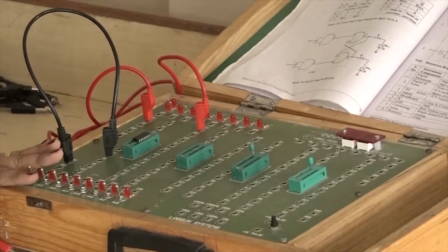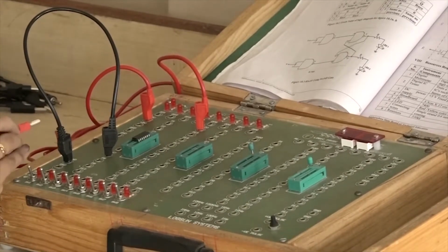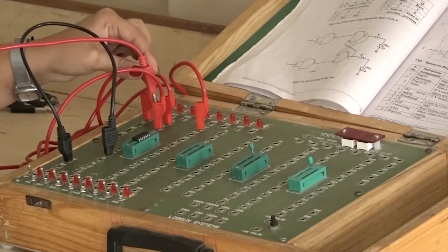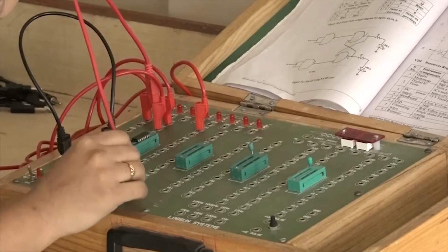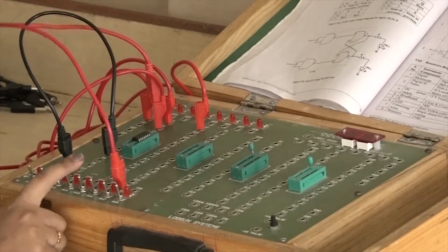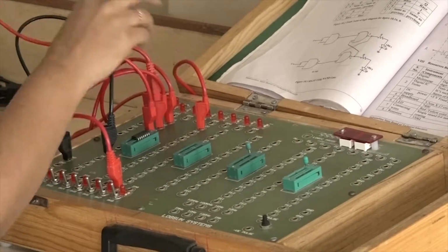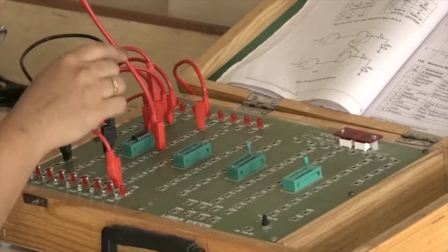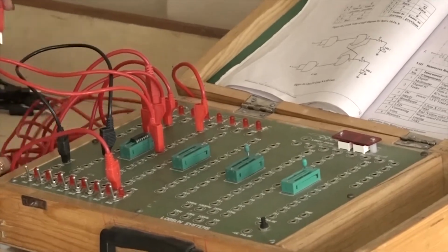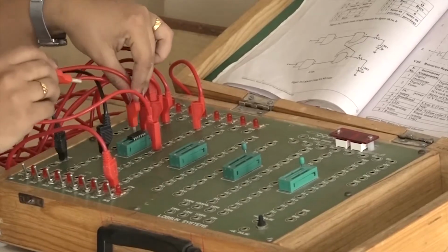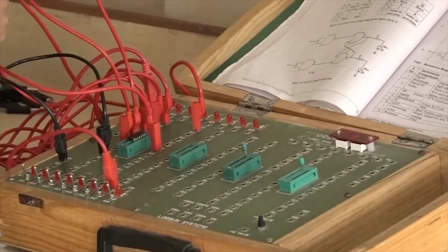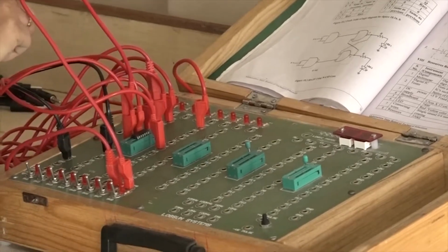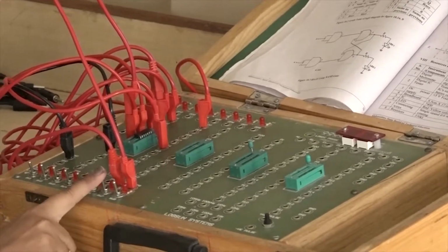There are two inputs, S and R, and two outputs, Q and Q bar. First, pins 1 and 2 are connected together, and they are connected to the input terminal, that is the S input. Then pin 3 of the NAND gate is connected to pin 10, the input of the third NAND gate. Now for the second input, the R input, pins 4 and 5 are connected together, and pin 5 is connected to the R terminal. So these are the two inputs S and R.